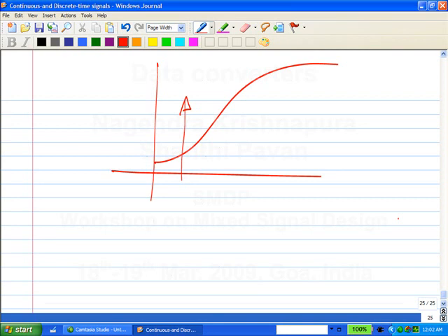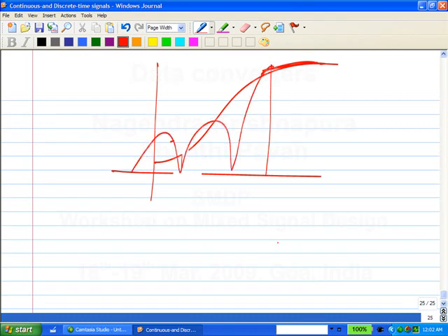Let's say the sinusoid is not even there. You try it out without an input signal. The problem is this noise will lead to this, because every one of these components will get convolved with something like this and it will appear here. If the actual thing is something like this, because of this noise and leakage, you may get something here. So you will be measuring more noise.